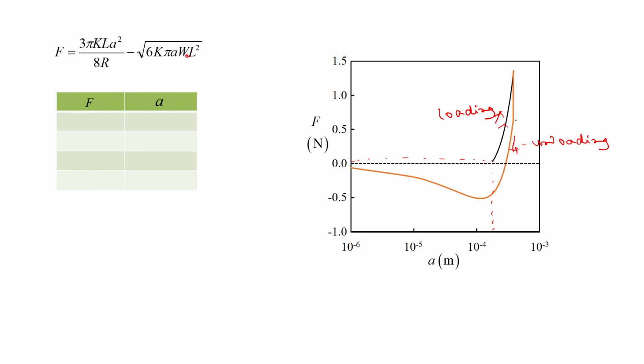decrease the load, and what happens is that the unloading data do not follow the loading data curve. It comes down like this, the load becomes negative over here, and then finally at some contact width, it goes to 0. So, basically what we say is that we get a minimum load. This negative means this is the pulling load. Here, capital F means this is the compressive load.